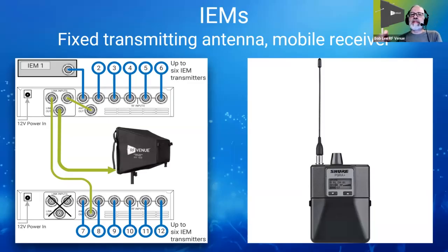This replaces the squelch adjustment used in some older receiver technologies. If you've used older wireless mic receivers or even some of the current ones, there's a squelch knob, or maybe there's an up and down, like you select different squelch values, and what you do is with the transmitter turned off and the receiver just listening to dead air, you just advance the squelch adjustment up until it mutes.